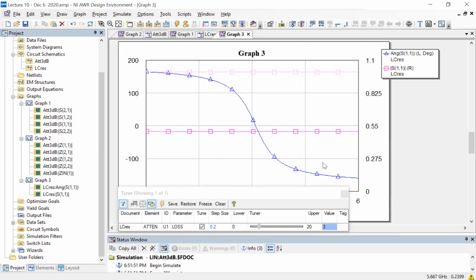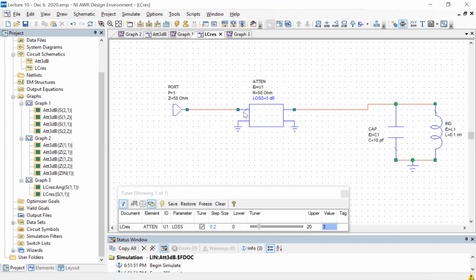But you see that with just 3 dB attenuation here, in terms of knowing about the resonance, things have not really changed, right? I can still see the resonance fairly clearly. Looks nice, and okay, I'm getting much less power out. And this is something very important to remember, that the moment you put a loss here, it experiences loss in both directions. So you get double the loss when you're doing a reflection measurement like this from one end. So it's much worse than you think it is. And this has consequences for signal to noise ratio, because you excited with some amount of power, and 3 dB less is going on.